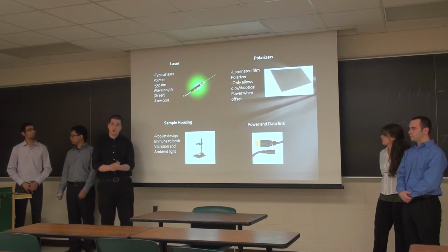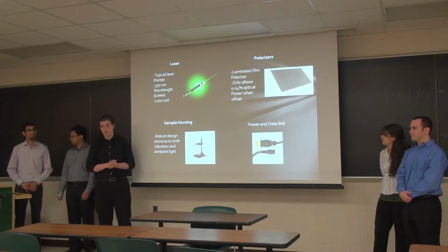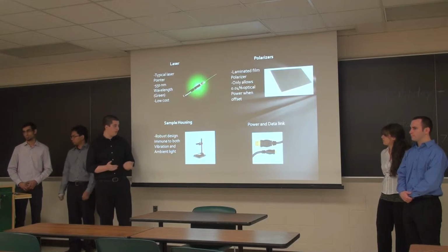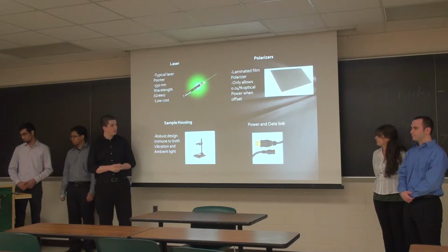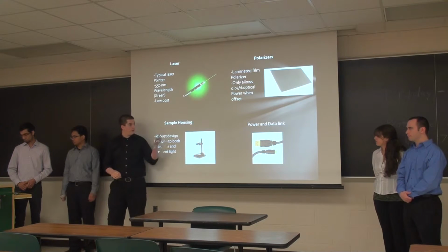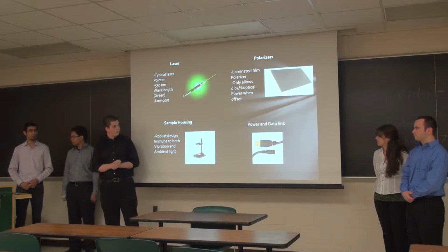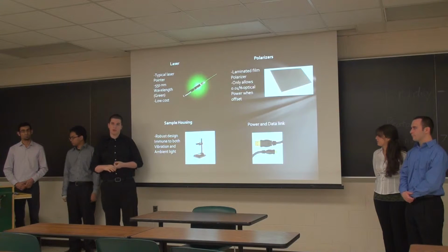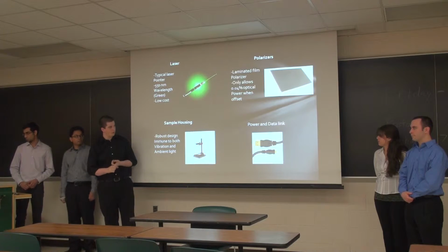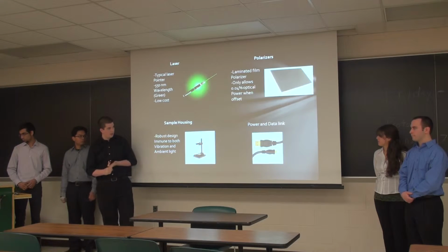Our sample housing, we're actually going to design in CAD and probably send it out to get 3D printed. We would do it here, but it's too expensive, so we have to send it out to a third party. And the entire design will have one micro USB to USB interface that both supplies power to the whole design, both the laser and the camera, and acts as a data bus between the two.